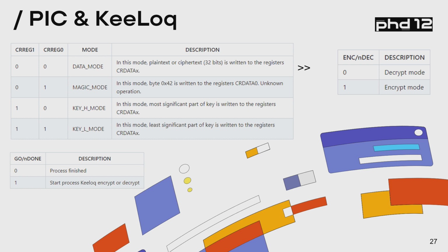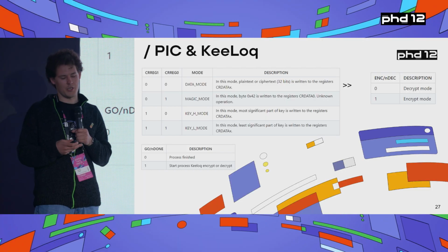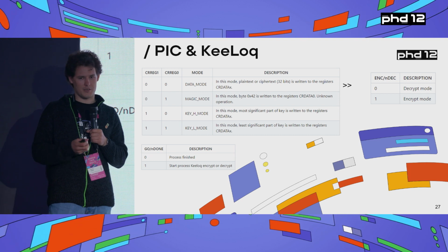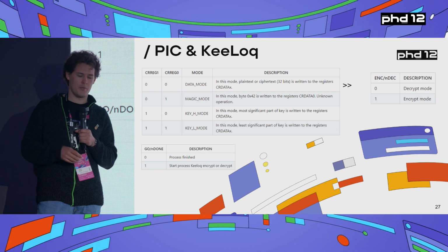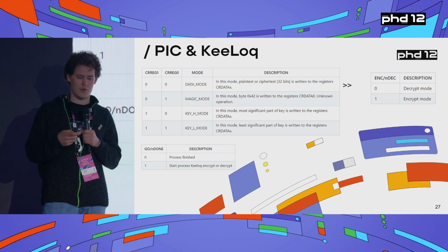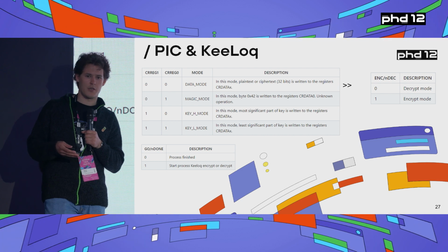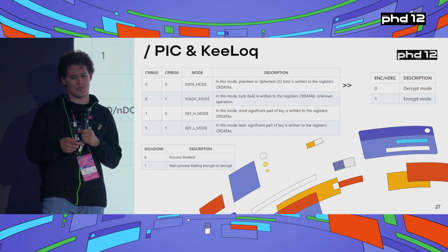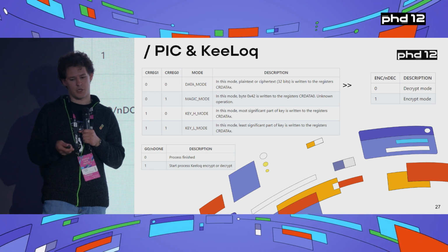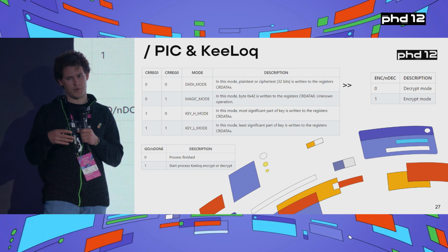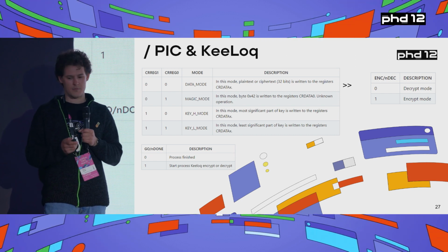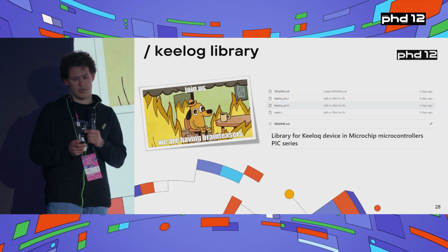And there are modes 2 and 3 responsible for writing 64-bit into key H. And the fourth one, which does what the table suggests. So using these 4 registers, you can write several elements of the key and do some magic stuff with the second mode, and then you can use the control bits to start the encryption process. Then you can check if encryption is over, and when it is, you can collect the encrypted data from the same registers where you put your plain text data.